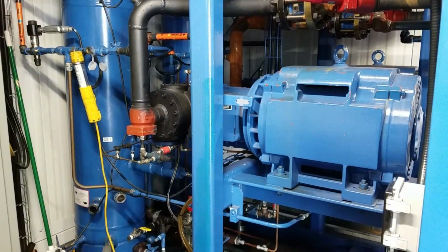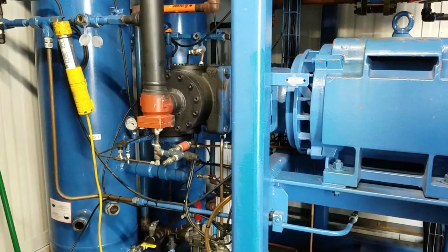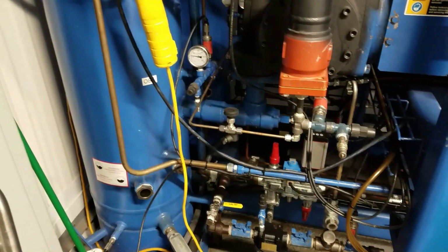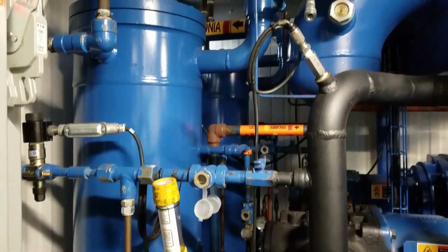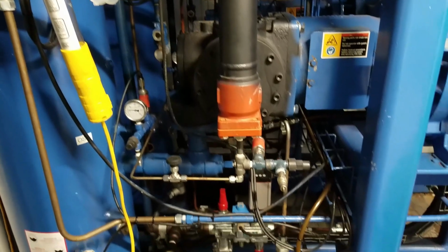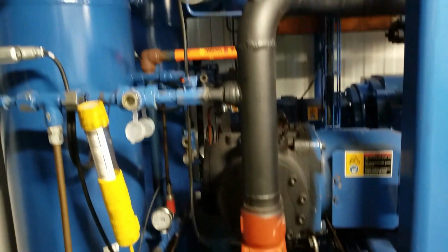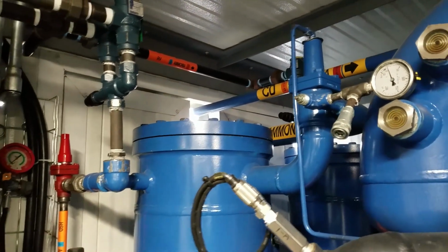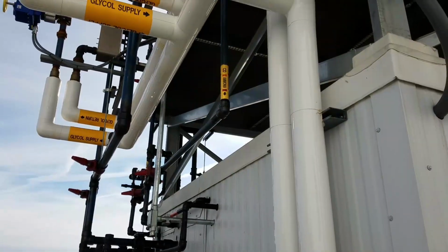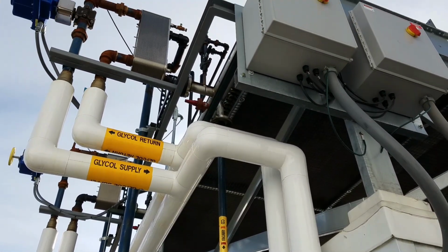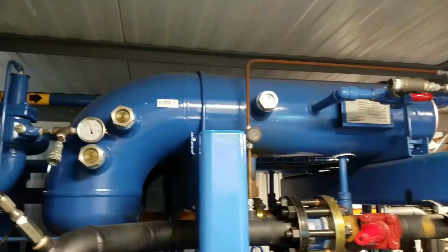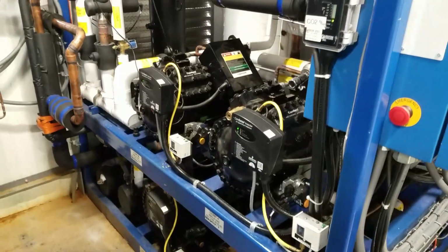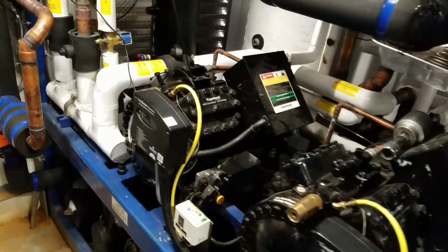Here's our ammonia skid, two single screw compressors with vertical separators. The oil that is being separated in our vertical separators is cooled by liquid injection. The discharge gas that goes out from our separator first goes through our plate heat exchanger, where we can harvest heat to provide a load for our CO2 evaporators, then goes through our air-cooled condensers and is returned in our liquid receivers.